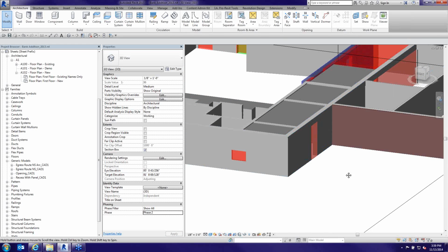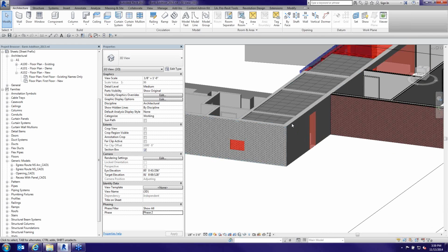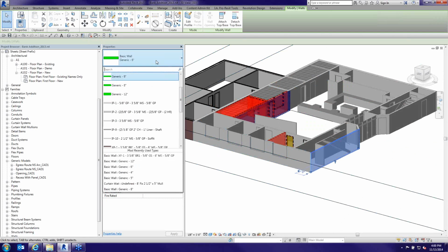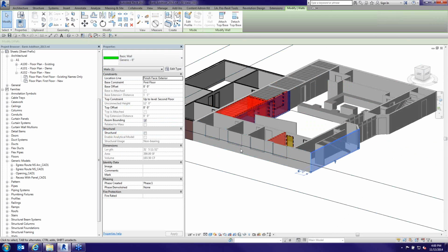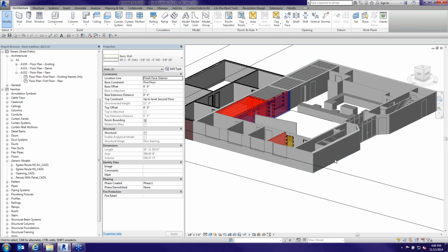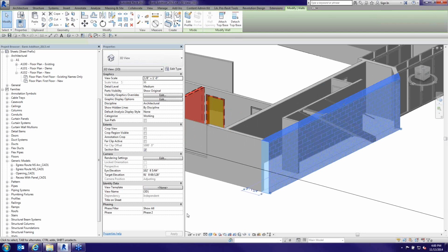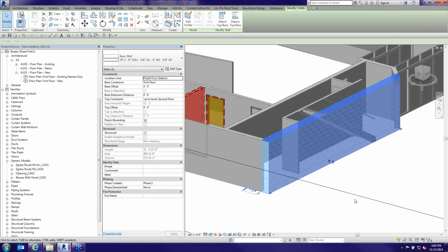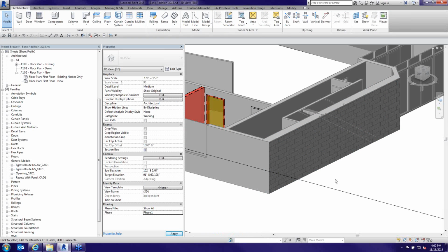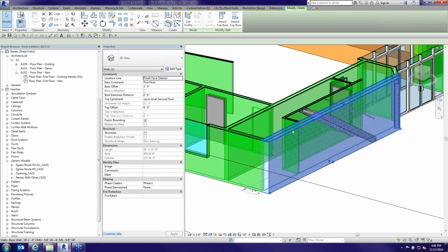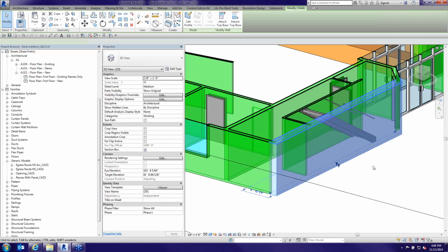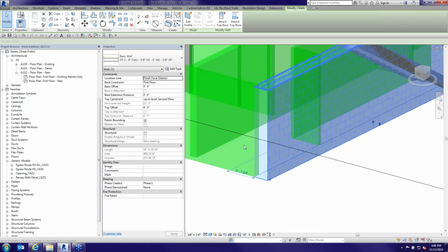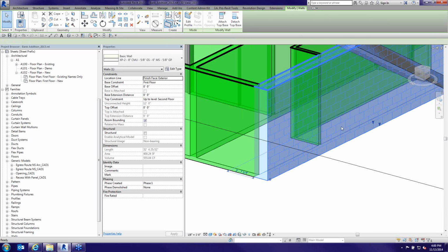The other way to do this is with an object like this. I'm going to convert a different wall to brick since that one's already been jacked with. We'll just say brick in here as well, or CMU, whatever. I'm going to go back and say this wall, we're going back to phase 1 view properties real quick. In phase 1, I've got this nice CMU on metal stud, so we'll just leave the CMU out here. What you can do is take a wall, and if you've never used parts before, you can actually part out a wall.